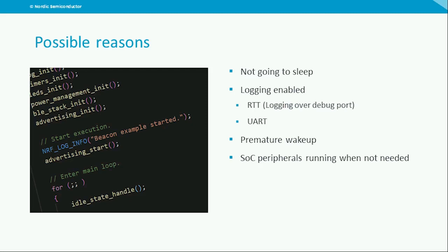And of course, having unused peripherals running that is not of any practical use. We've seen it time and time again, that a developer might do a lot of testing to begin with, turning on modules for testing and forgetting to disable the ones that will not be needed in production, or having configured something to run a lot more than needed. Plan the structure of your software carefully, so it always is easy to give it a read-through to see if there are any places where we can remove or change parameters that will utilize the peripherals more than we need.